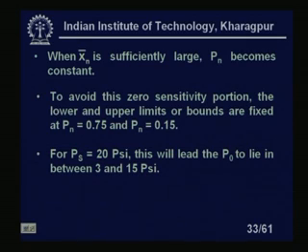For a supply pressure of 20 psi, this will give 3 to 15 psi. This is the key reason you will find this value in all pneumatic systems. Many a time we call the industry standard 3 to 15 psi of control pressure, and this is the point where it actually came from. We want to stay within this range because it takes the linear portion of our graph. So, the flapper nozzle system will be linear in this region, and that is the reason we are limiting this pressure.